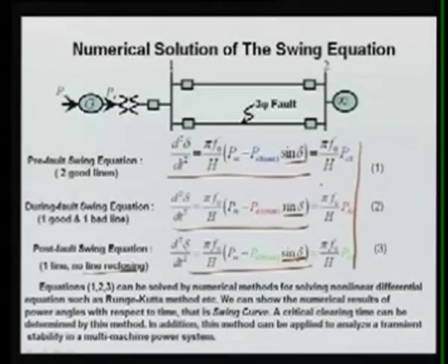But the only limitation is that we have made several assumptions. Those may not be valid for a big power system, and also it is not possible to reduce the system to a single machine infinite bus equivalent. Then we have to go for the complete, real-time practical system for the simulation, and for that we have to solve these differential equations for all the machines, not only one machine. This is the case of one machine.